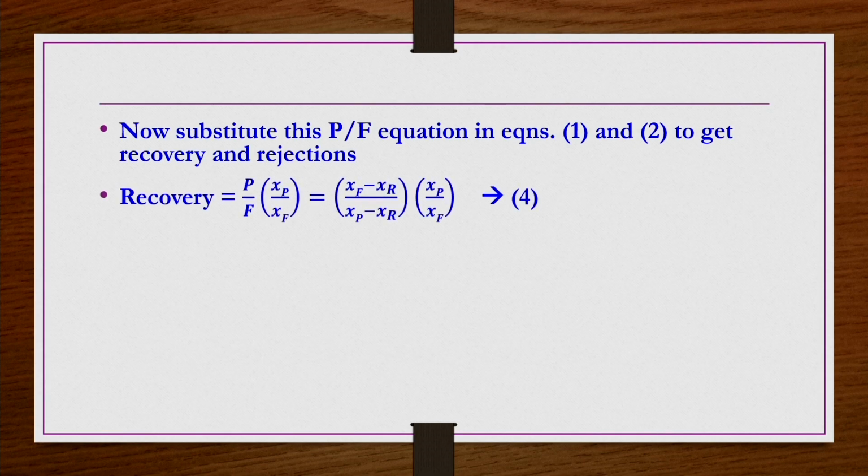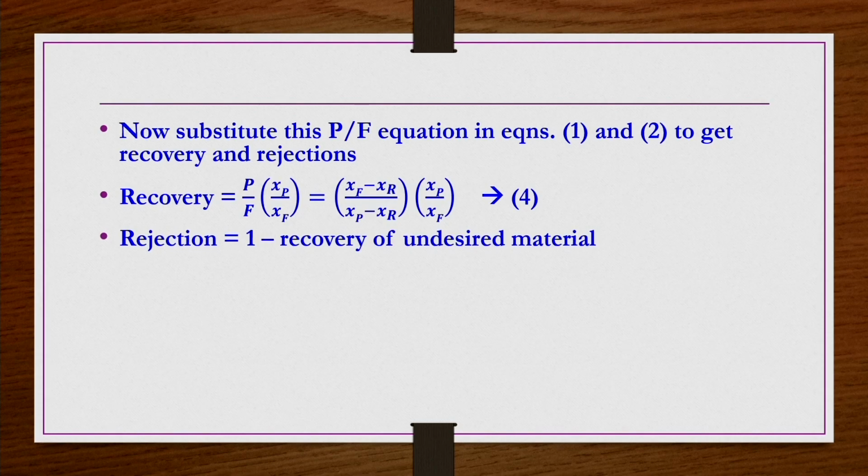When you substitute this P by F in equations 1 and 2, you get recovery as P by F times XP by XF, equal to (XF minus XR) by (XP minus XR) multiplied by XP by XF. Rejection is 1 minus the recovery of undesired material, which comes out to be 1 minus (XF minus XR) by (XP minus XR) times...